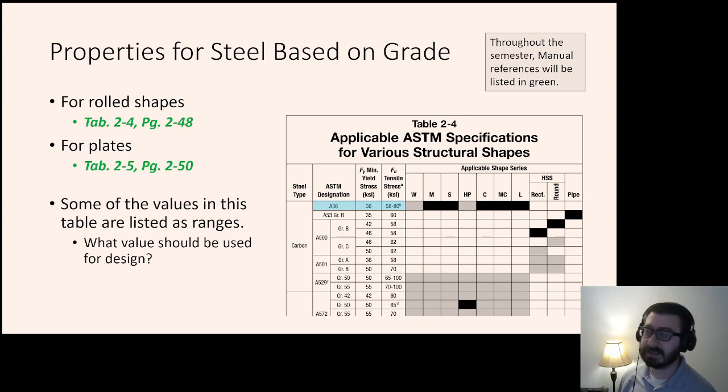One common place that ductility is very desirable is in seismic applications, because you have a lot of energy that gets applied to buildings under an earthquake, and so we want materials that are very ductile. We don't want them to suddenly fail in a brittle mode. We want them to be able to absorb that energy. With some materials, you get a range of behavior, and so you need to understand how that might affect certain design scenarios. That's why the range is reported. So in case you were wondering, that's the answer there.